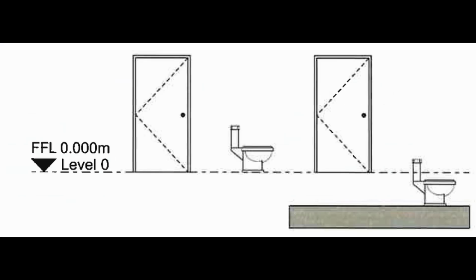Component placement. Components can be hosted, placed on walls, ceilings, floors, roofs, or faces. Level hosted: freestanding elements placed on a level. Work plane based: placed on any defined plane. Even freestanding components can sometimes detect nearby hosts. For example, a toilet placed on a level may automatically adopt the offset of a floor slab if that slab existed before placement. But this behavior does not apply to all categories. Hosted elements like doors behave differently.